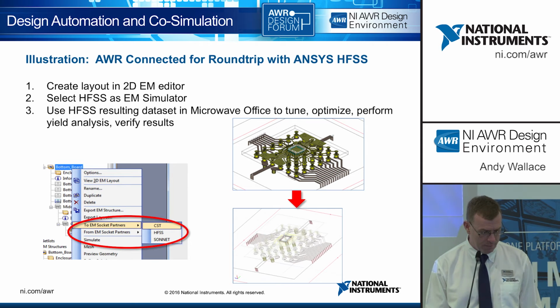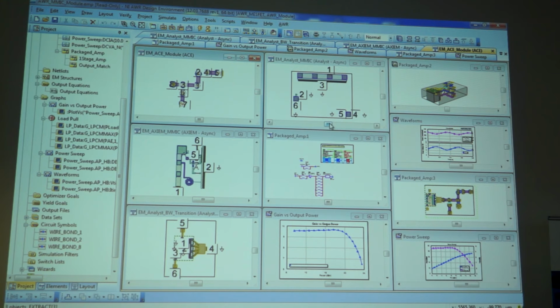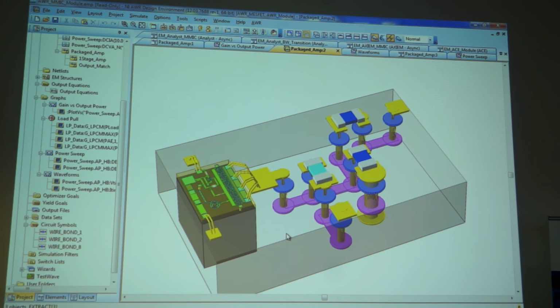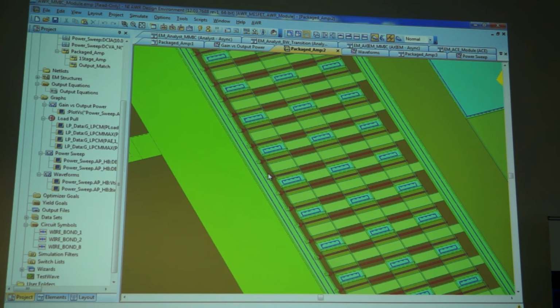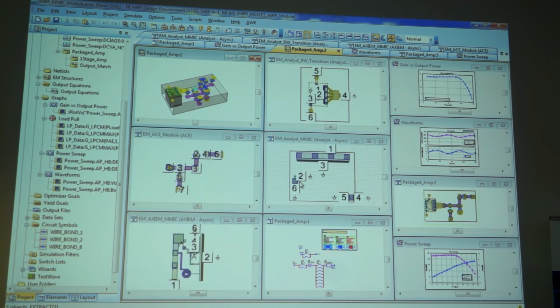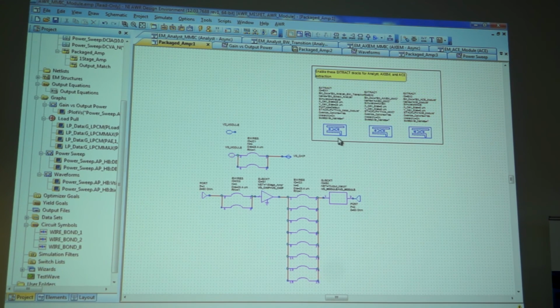I've got another example just here, if I can find the right one. So in this particular design, I was looking at a multi-technology type design. The idea is we have the matching circuit on the laminates, we have ball and stitch bond wires up onto a chip, multi-layer technology for the GaAs FET fingers as well as surface mount device chips. And what we were looking at on here is the idea of running not just the circuit level tool, but EM extraction. And at the top level here, you might see that these extract blocks point to different engines.